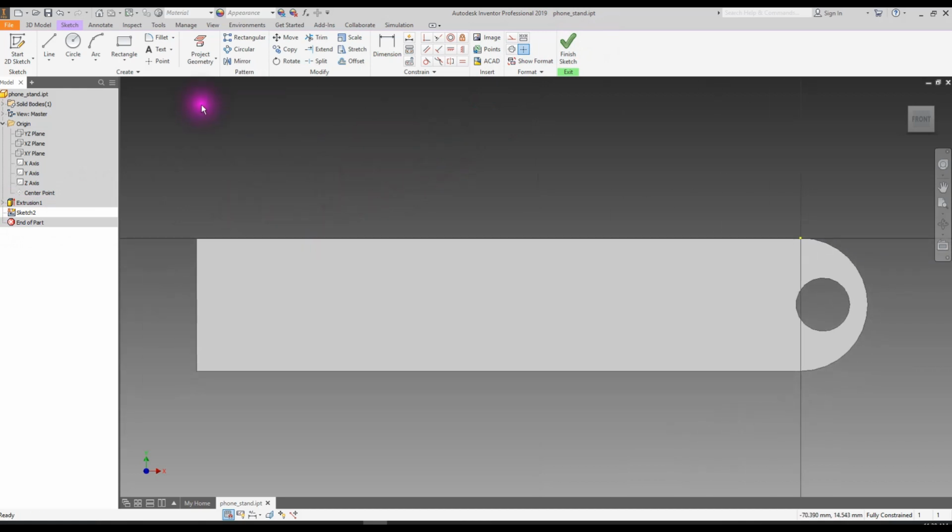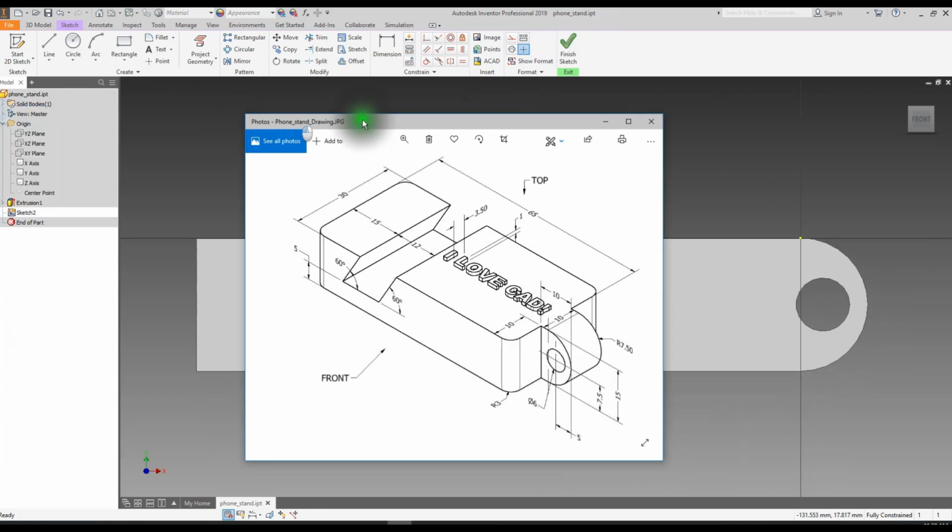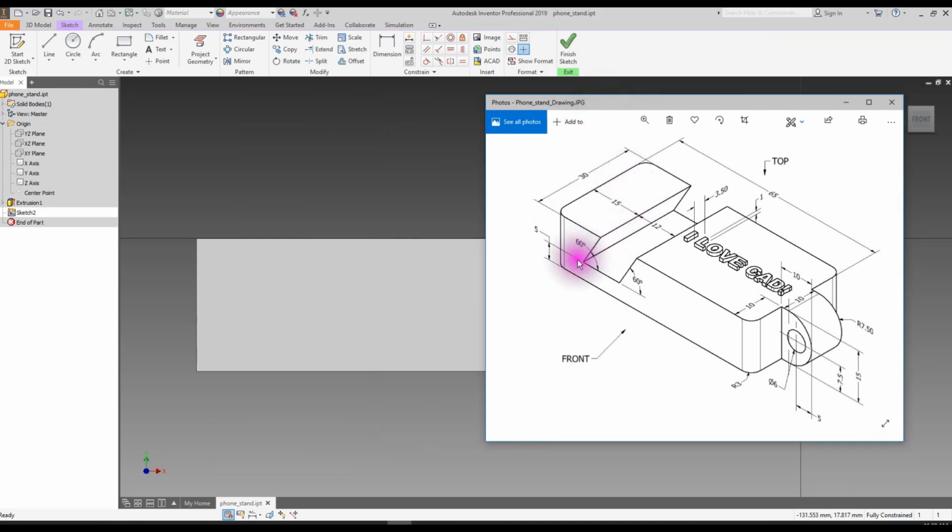So what we want to do now is bring in the drawing. We want to make this cut here. So we will sketch this section, and then we will cut it using the extrude tool, but instead of adding material, we will remove material. So we need 2 lines, or actually 3 lines, plus the top, 4 lines all together, and they need to be at a specific angle and some specific dimensions. But let's worry about the dimensions in a little bit.